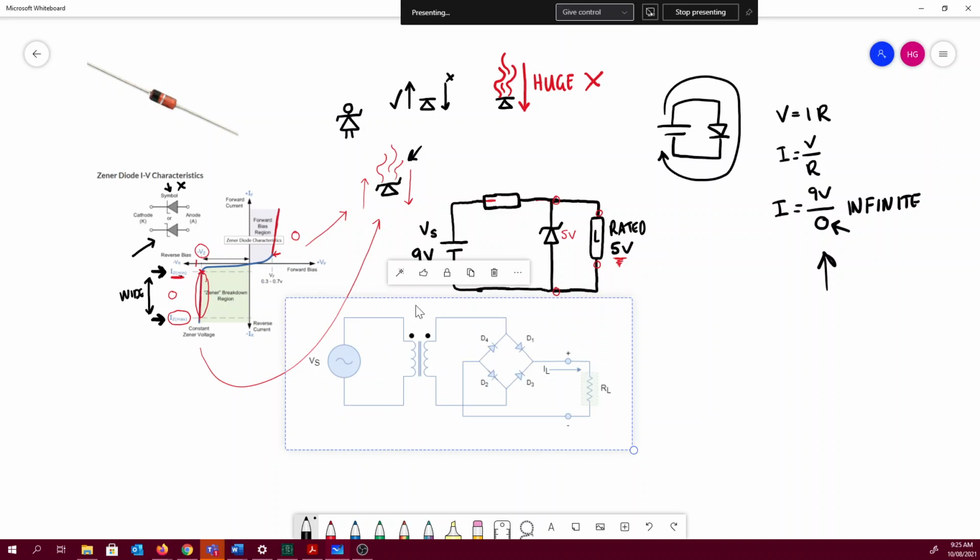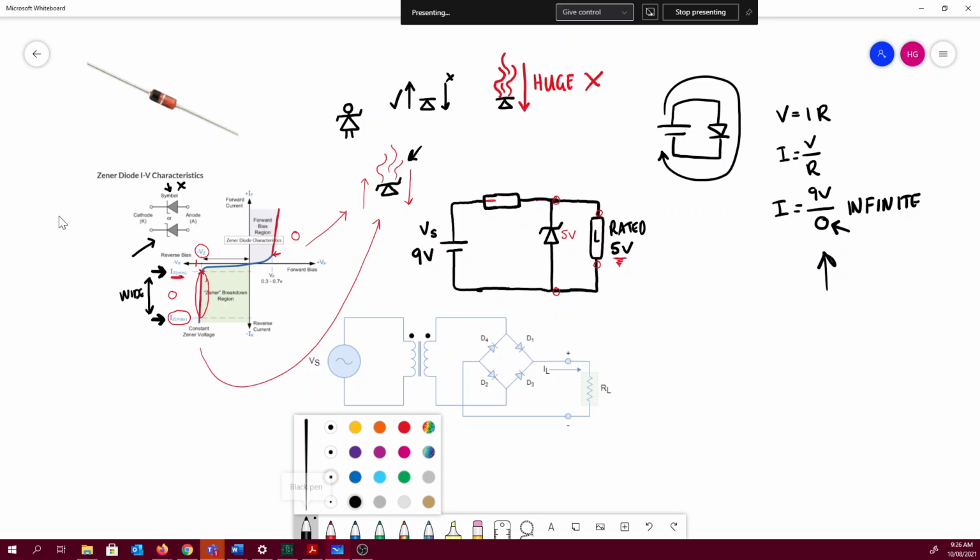Okay, so we've got a bridge rectifier, and we can see that in order to make nice DC current, this bridge rectifier is actually missing something straight off the bat. Can anybody, for a bit of revision-y goodness, tell me what this bridge rectifier circuit is missing if we don't want terrible lumpy DC? It is missing a capacitor.